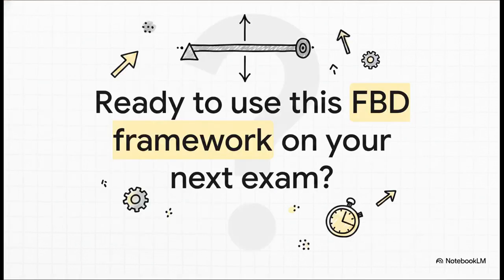You now have the exact sequence to break down any static equilibrium problem. Define your equilibrium goal, decode your supports into arrows, simplify your loads, and systematically solve the diagram. So now that you're armed with this repeatable solving pattern, how are you going to deploy it to completely crush your next engineering assignment?